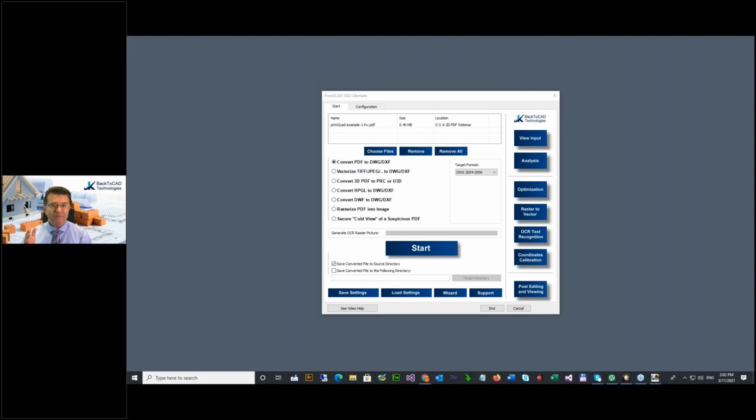But very important, you have to activate the correct parameters, because raster to vector is a very complicated task, and you do not have only one kind of scan. You have different scans with different drawings, and you have to tell our program what is most important for you, what you expect from this raster to vector. This is very important.